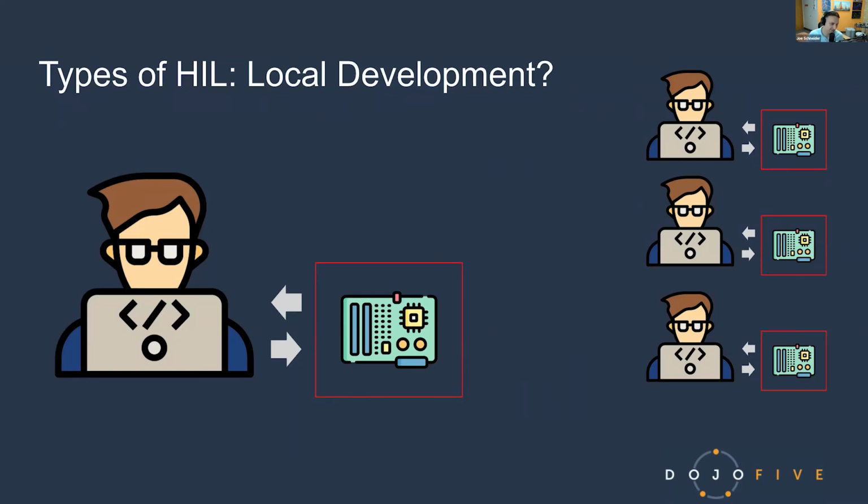We were able to build a HIL around this device that we could constantly cycle it through. And we had to actually pull out the OS and go bare metal, running memory burst tests in a cold chamber, bringing the whole board down to -40. Eventually we got it to fail in a way where we could actually say, hey, look, your memory is failing.